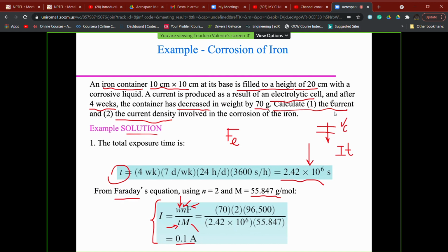have 0.1 ampere as intensity on 1 square meter of surface, or 10 square meters of surface, or 100 square meters of surface, and obviously the reduction in thickness, being in this case a uniform corrosion process, that is the severity of the corrosion phenomenon, is different, decreasing as much as the surface is increased, and so we need to take care of the surface and the measurements in terms of current density.